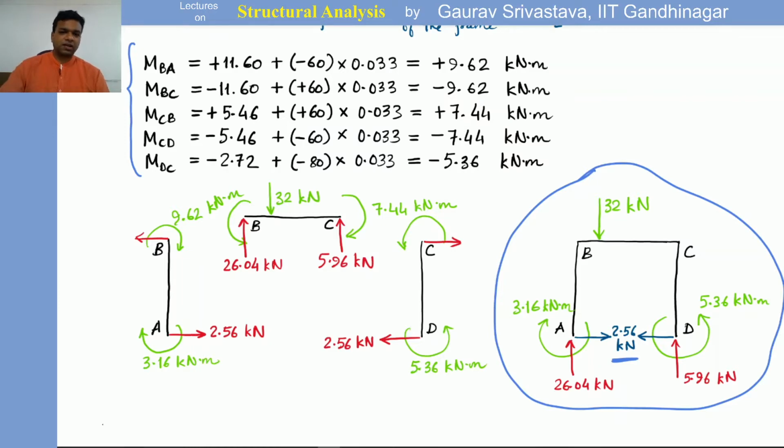So in the earlier case, when we considered that no sway was happening, this free body diagram was not actually in equilibrium. Okay, so that prompted us that there is something more to it, and that is where we undertook the sway procedures. So we considered the only sway part, and we applied a force which was the imbalance.